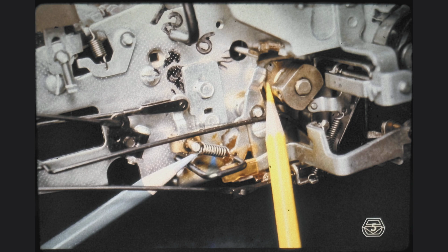The resulting motion of the cam follower is then used to operate some output mechanism. In this case, it is used to select a low-velocity cam for the printing operation. The point at which the selected latch releases the cam follower is located exactly behind the strong driving spring indicated by the blue pencil. Furthermore, in negative mechanisms such as this one, the cams are used to restore the spring tension, which provides the power to drive the mechanism.